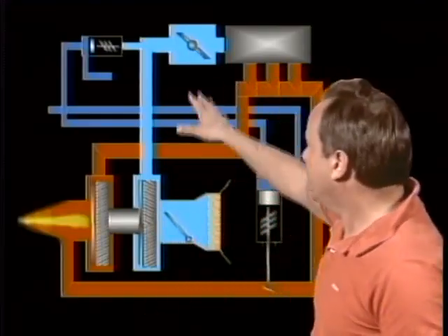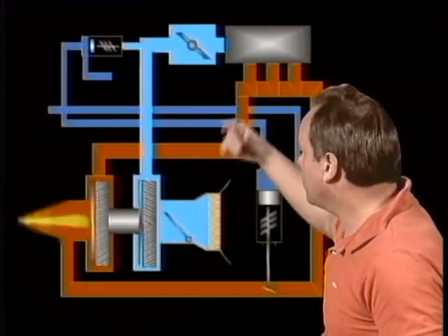All right, now what is the purpose of a rate of change controller? Well, if you have a turbo-normalized system, you also have a rate of change controller, and what it does is control the rate at which the turbocharger discharge pressure will increase. It just will not allow the turbocharger to increase or decrease rapidly. That's the rate of change controller. It just smooths things out. That's actually part of the density controller.